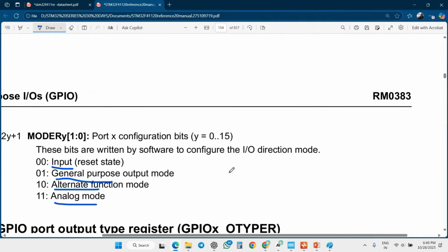That means you can take an input while setting 0 0 on that specific bit. We can set the output when you're configuring LEDs or motors, because you are going to give the command. So whatever peripheral you want to configure in output mode, you can also do this. That GPIO pin, you can configure as an output mode.